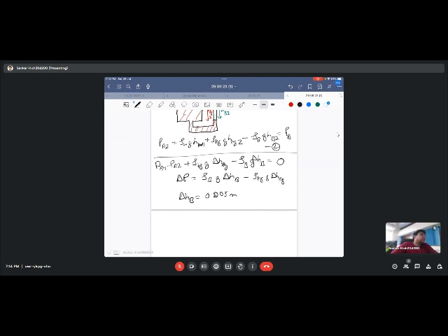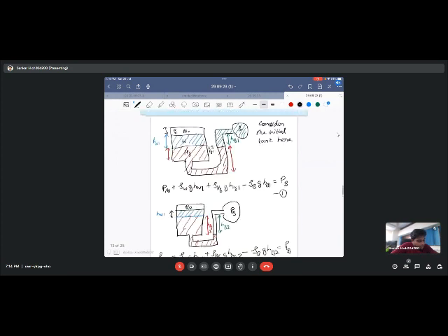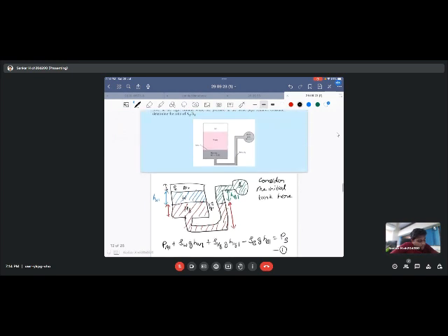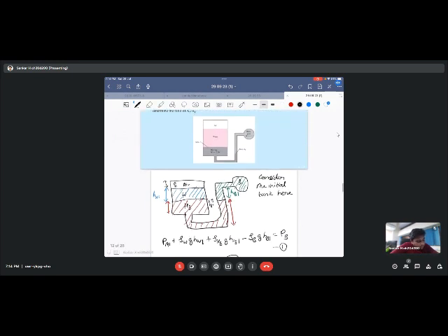And therefore, if the brine solution has dropped by 5 millimeter, we also need to understand that mercury will also be dropped by 5 millimeter in the right limb. But that does not mean mercury will rise the same amount in the right limb. It just means that the volume of mercury that has changed will be the same as in the other limb.